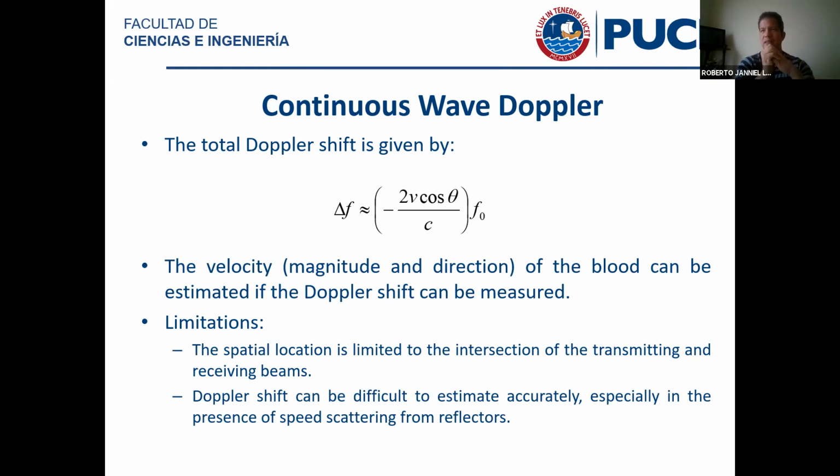So in this case, because there are dragging forces, and there are many ways that these dragging forces come into play, the idea is that the fluid cannot be super quickly marching along while the walls of the pipe are rigid and stay in place. So you're going to have a profile in the velocity. You're going to have a different velocity at the center than the one that you have towards the inner diameter of your pipe.